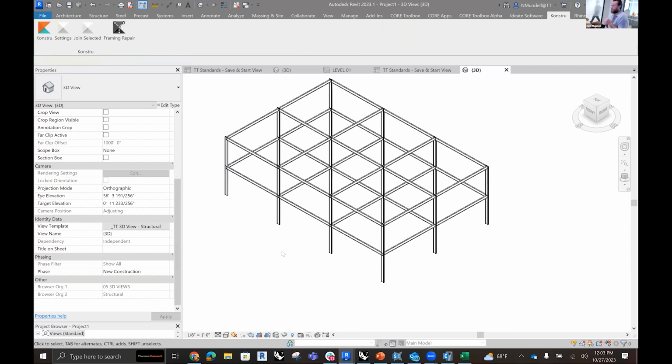Okay, so two one-way translations with a little bit of a round trip in there, showing you how to go from Revit to analysis, how to go from analysis to Revit with a little bit of Excel in the middle.